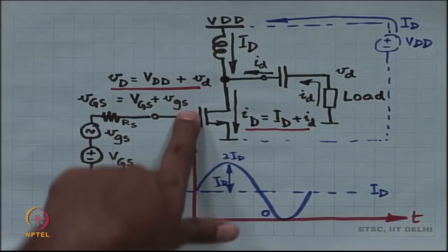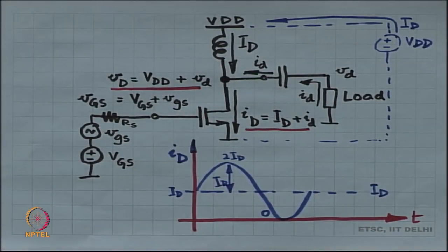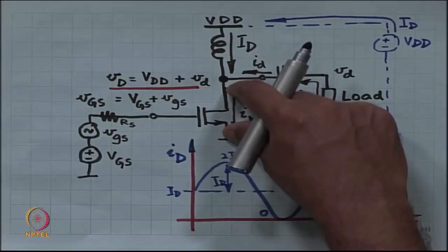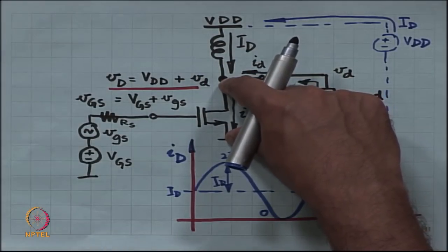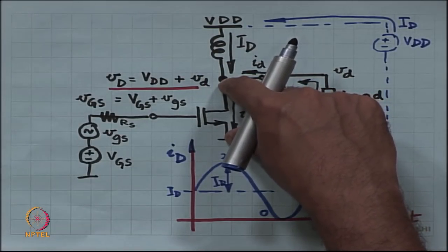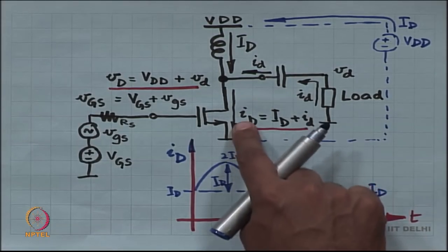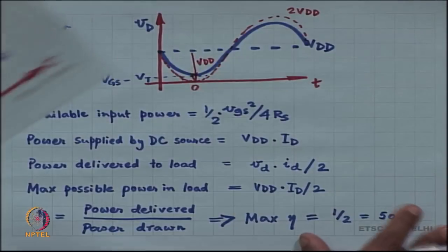This is just the load and the MOSFET. Let us check what is the power consumed by the MOSFET. How will you do it? How will you work out the power consumed by the MOSFET? The power consumed by the MOSFET is the voltage small v sub capital D times the current small I sub capital D.